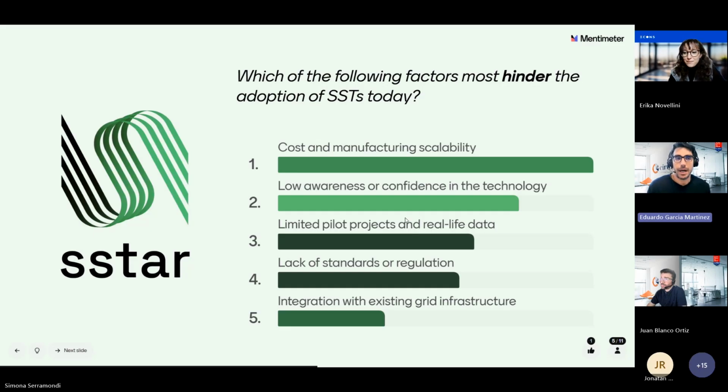We are seeing a lot of movement regarding that, in order to increase at least the integration of photovoltaic, of trains, of data centers in medium voltage DC. And it's where this SST technology is going to increase its reliability and reduce the cost. It's the place where this technology is going to be introduced in the market.